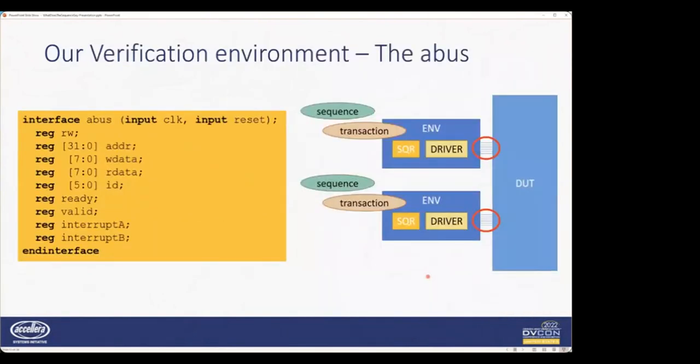All right, getting back to our environment that we're trying to use to verify our hardware. We have a little bus here. It's not so important in this talk, but it has a read-write bit, some address bits, a byte of write data, a byte of read data, an ID, ready valid signaling, and 2 interrupt signals.